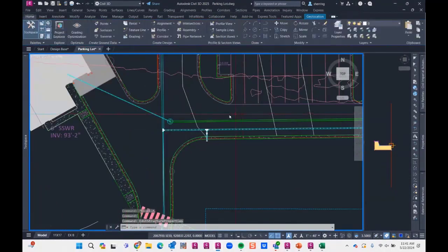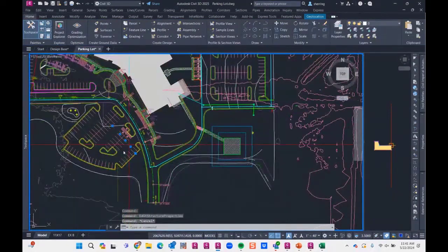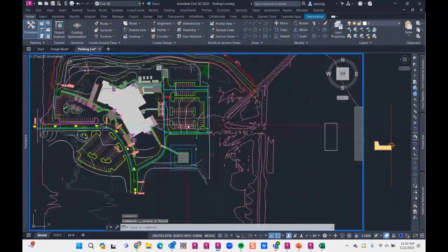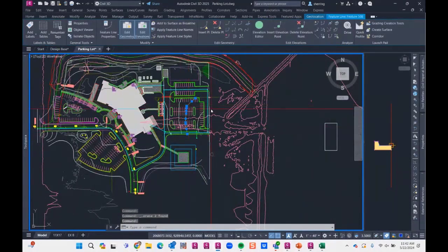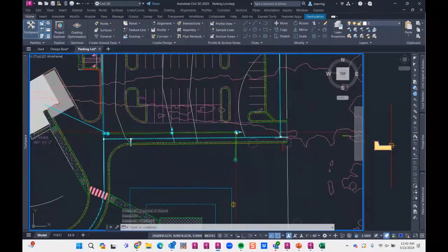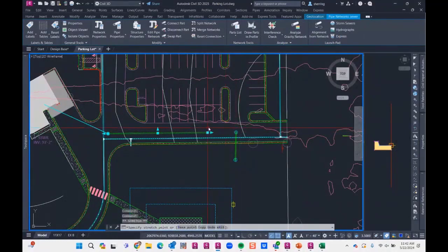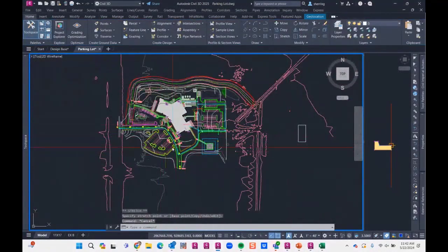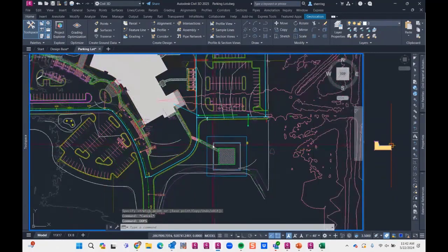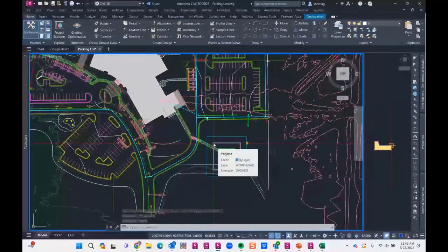4940. Let's get rid of some feature lines. There's a command that somehow I've started using a lot more lately. Let's say we deleted something accidentally and we're coming in here changing pipes, doing some work, and like, where'd those lines go? I didn't mean to delete that. There's an oops command that just goes to the last thing you deleted. I always accidentally delete stuff and then I have to go undo. So it undoes to the last deleted.